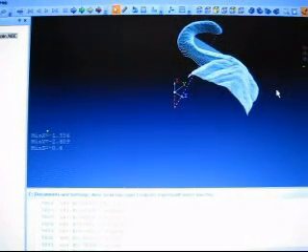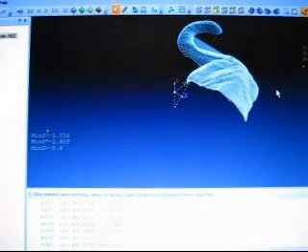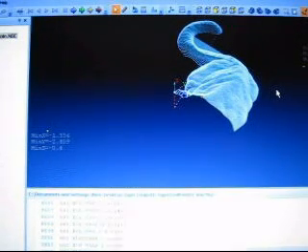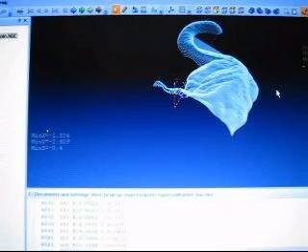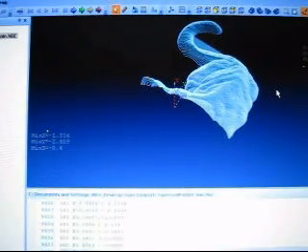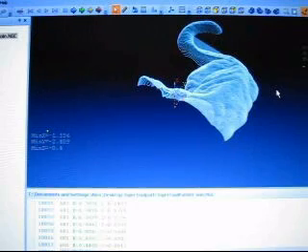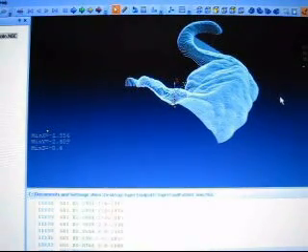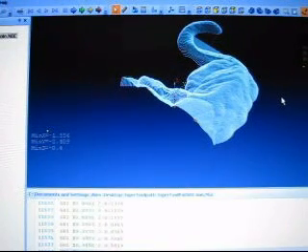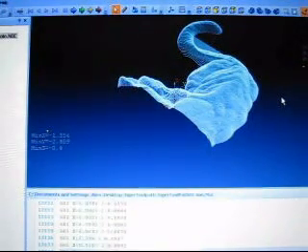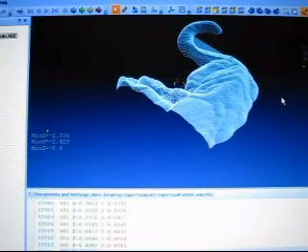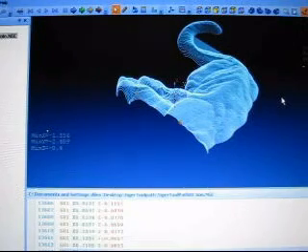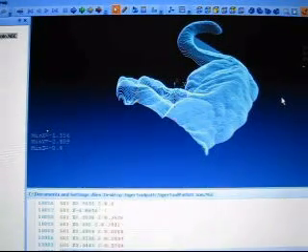Alright, now if you follow this step by step, you're going to get these results. If you wanted to create a toolpath on all those millions of lines, you're going to get rapid motions all over the place. It's going to go from one area of the part to the next. It's not going to scan directly across the part like it is nice and smoothly now. This is what we want. We want it to scan across this part in an orderly manner. That's why we took those steps to get to this point.